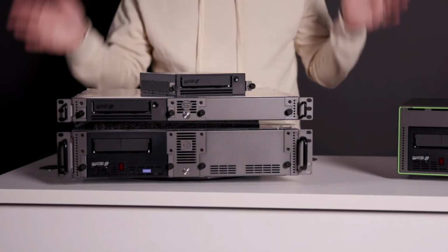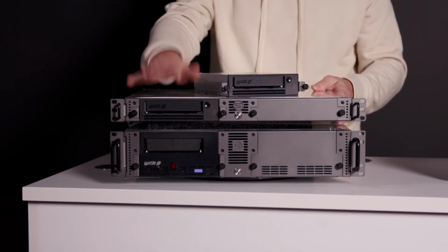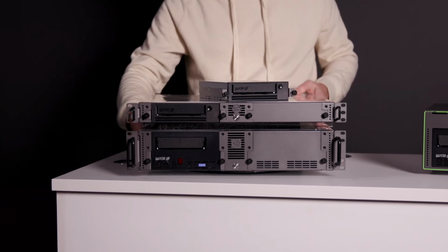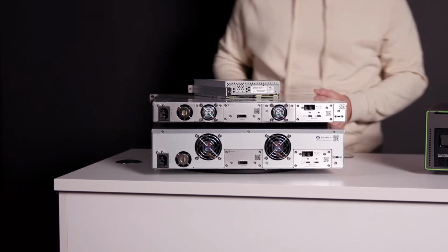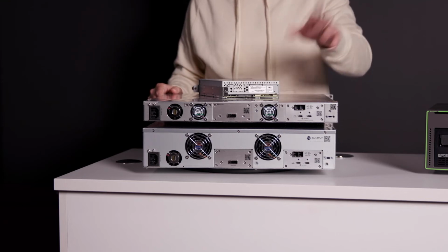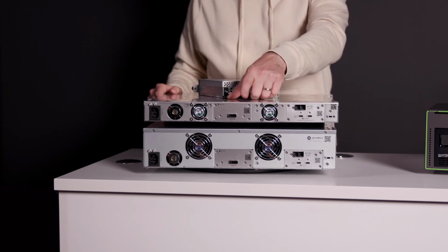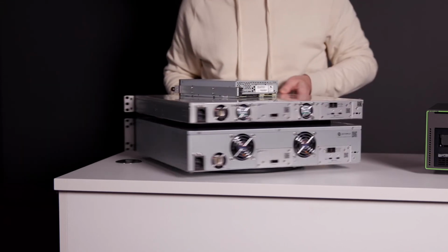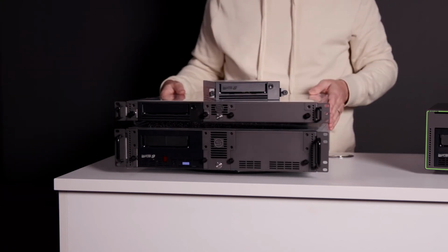Again, everything that I've shown you here is the same with the rack units. We've got our 1U and 2U with either one or two drives, half height in the 1U, full height in the 2U. If we have a look at the back of the units, you'll see we have the same layout: our Thunderbolt ports, again, charging. We've got our SAS expansion ports, so you could go to a SAS autoload or a tape library within the same rack and bridge that to Thunderbolt. And then we have our SAS connection here that will allow you to connect to a SAS server. Again, that's common across both units. Both units are also installed with the same cableless design technology, which allows you to swap the drives at will.